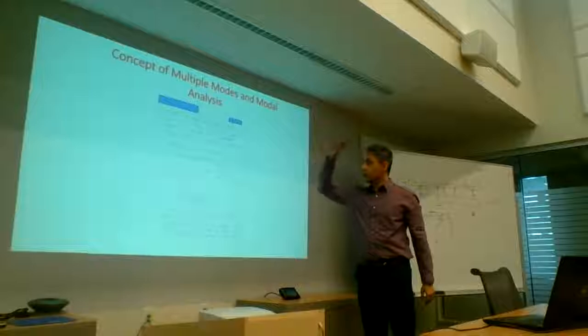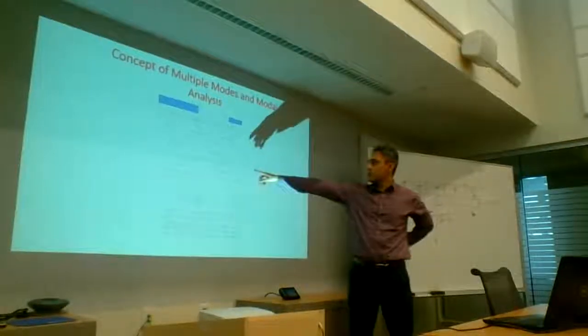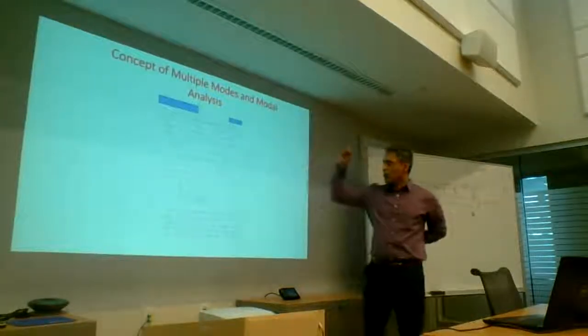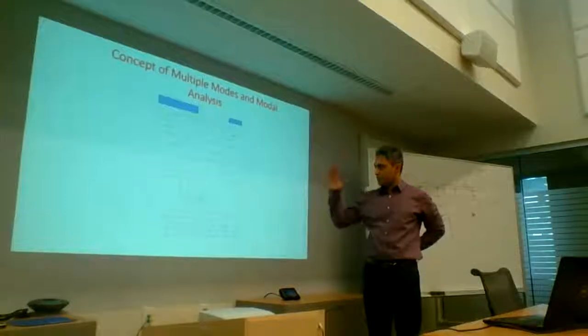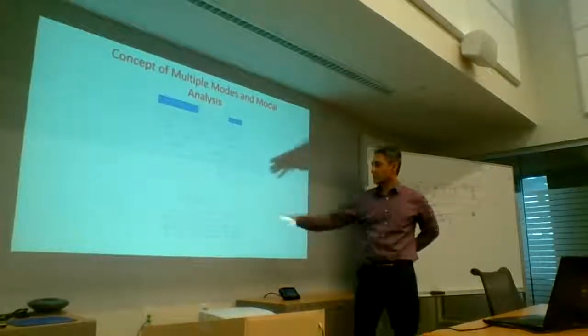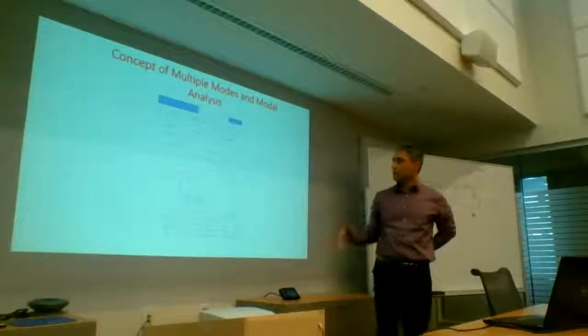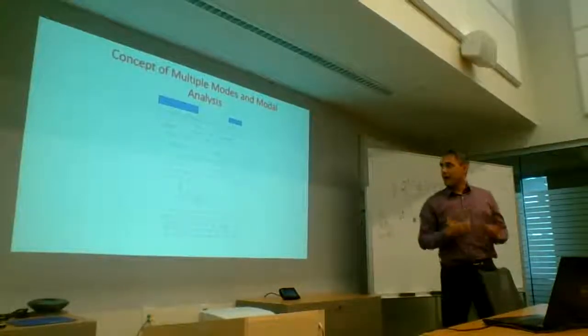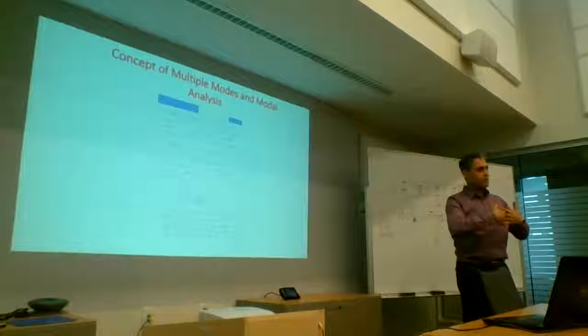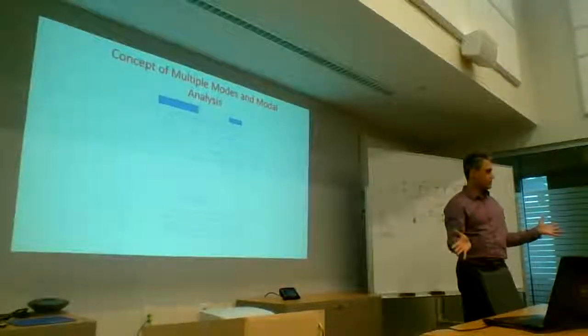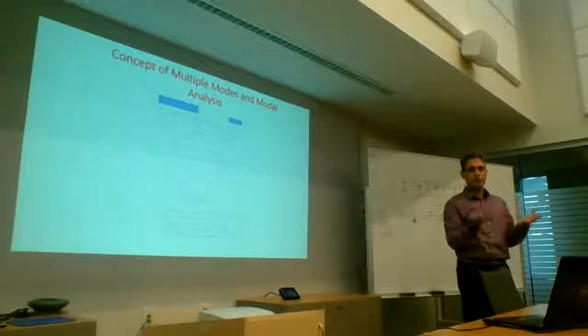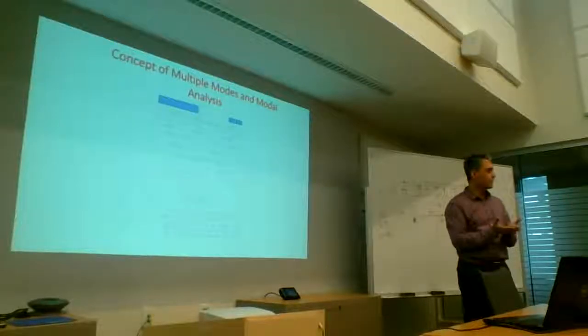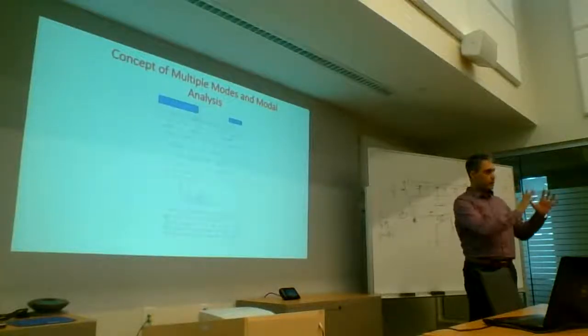So this is giving you the equivalent equation of motion for a single degree of freedom system. This is one of the many that you've decomposed the system into. The advantage is that these equations of motion have been decoupled from each other. So there is no need to solve them together. They are in their own coordinates.